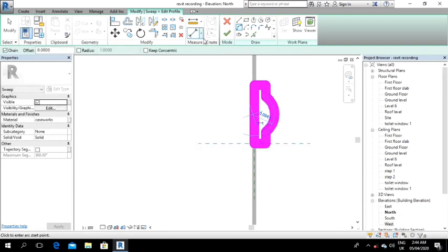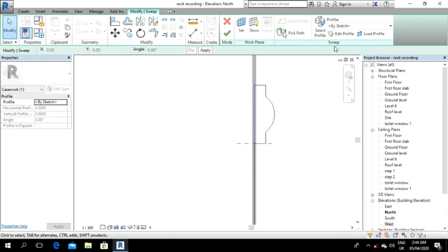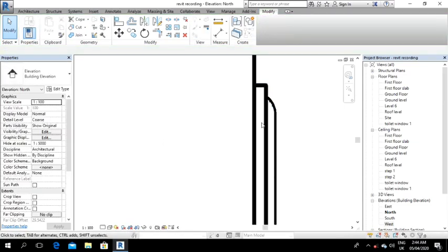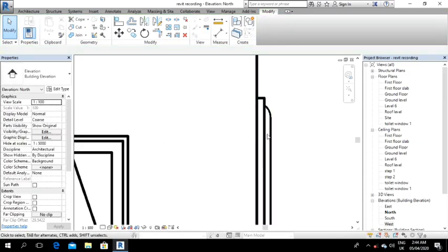Alright. Use the trim section to make sure everything is connected, because you can't afford to leave a loop open. Alright, check it. Remember our casework material. Then check it once more. You can also change the material here. You can see. Okay, and finish. So that is it. So the next thing is to copy it to the different window types.